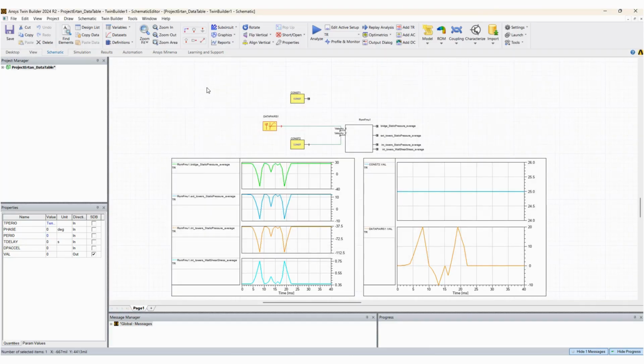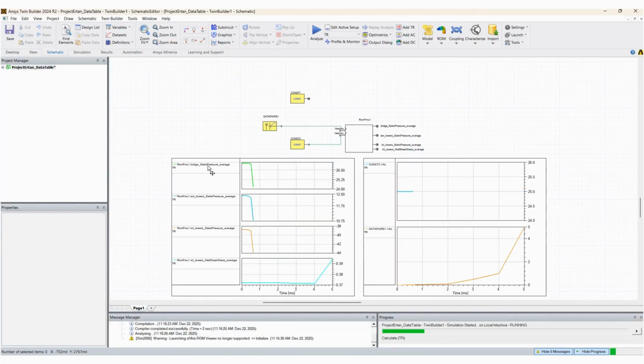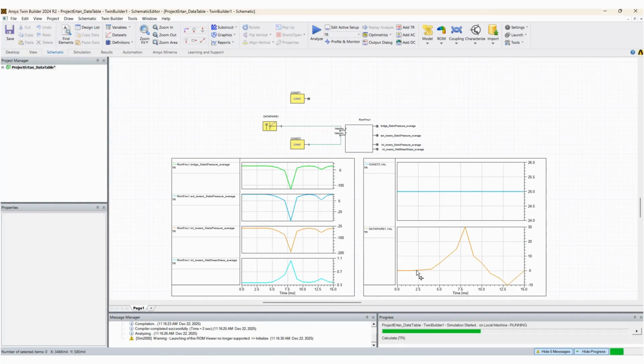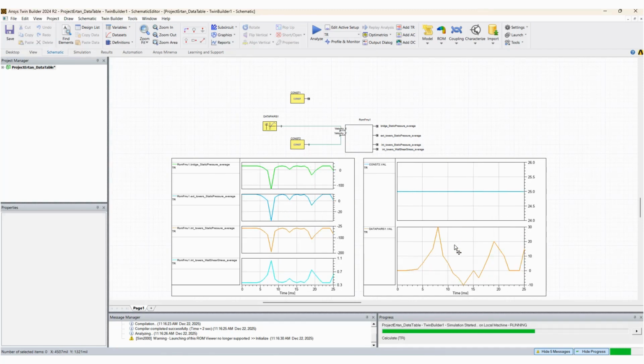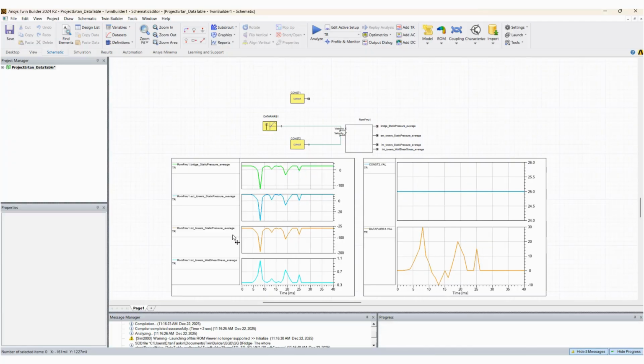say OK, and then similarly when we hit the analyze button, in this case you see that I brought the inputs also. So inputs are on the right side. You can of course change their locations, and outputs on the left side. And so one by one the data is read, and the corresponding response with the static pressures and wall shear stresses, etc., are shown on the left.